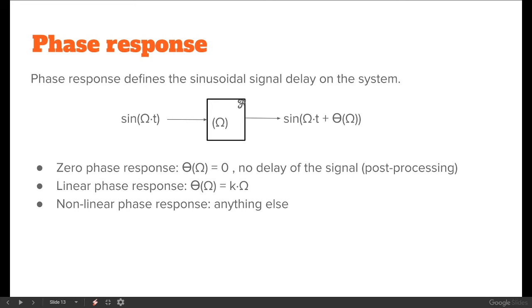So you get some wavelength dispersion in air in any case for voice, which means it does not matter if we have some more dispersion due to the system. So we can use IIR for audio recording. With some careful design, you can actually compensate the dispersion. But I cannot think of any use for that. But you can.